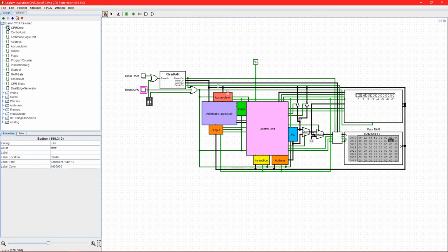In a future video, I intend to implement stuff like interrupt handling. So we will be able to set an address for the interrupt service routine, enable, disable interrupts, clear the interrupt flag, etc. This will require an extra ROM for the instruction decoder and a few other things that I'm not quite sure how to do, but this is a good start, and I would like to leave the CPU in a state that can be run without error at the end of each video.